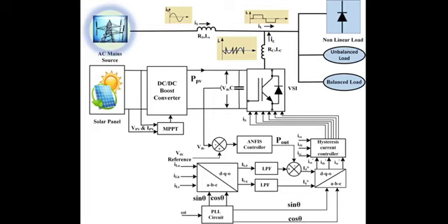Power quality filters. Power quality filters are designed to address various power quality issues such as voltage sags, voltage swells, voltage flicker, and other disturbances. These filters help maintain stable and high-quality power output from the grid-connected system. Low-pass filters. In certain applications, a low-pass filter may be used to smooth out rapid voltage or current fluctuations and prevent high-frequency components from reaching the grid.